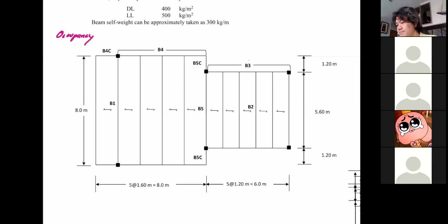So with that said, the floor will support how you're going to use your structure, and then the beams in turn will support the floor. You have to find a way to transfer the load from the floor onto the beam, and the beam will move the load to the column. When the load reaches the column, it goes down to the foundation. So the job of the floor, and you as an engineer for the floor system, is done.